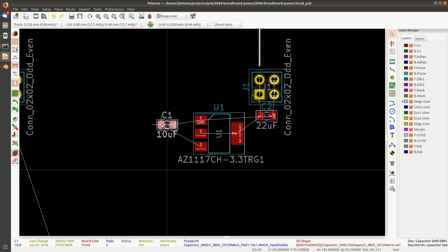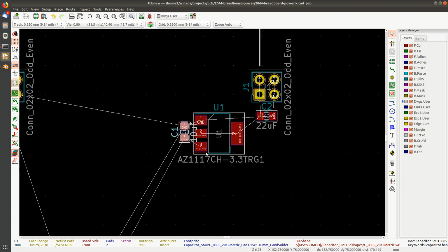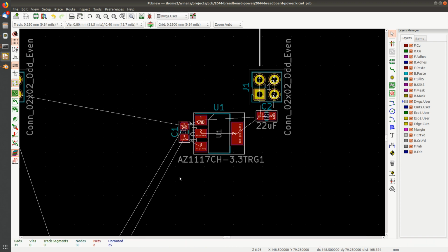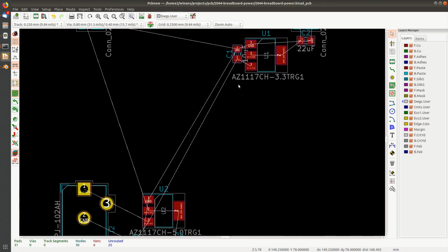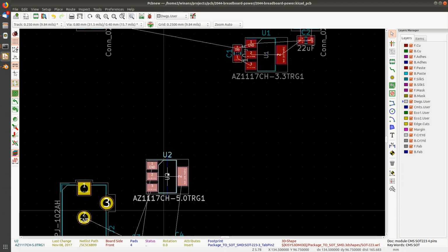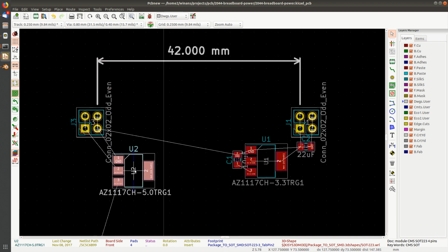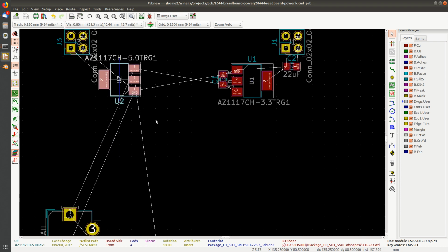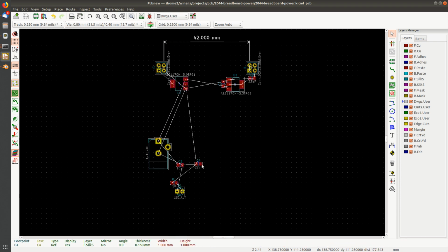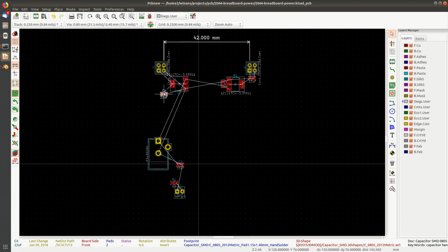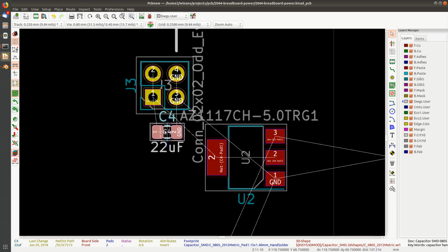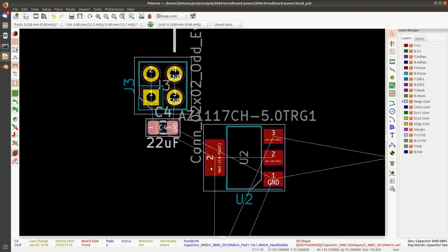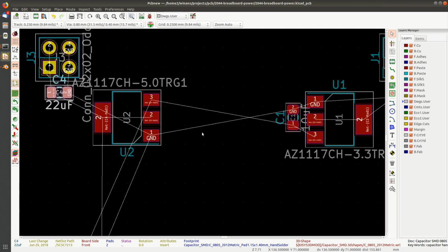And now I want this guy to go in there, and just like in the schematic, you can rotate these things around. This is going to connect those 2 outside pins in my regulator. All right, so that's roughly a good place to put that one. Select it and hit M. Now we're kind of symmetric, so I could probably flip it over and go the other way and do the same thing. Oops, there we go. Move this guy. Now this is the same thing as the other one. We'd probably want to make it look symmetric, like we meant to do that.